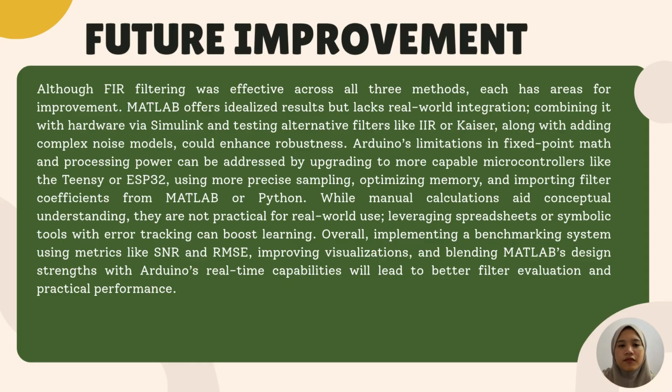Arduino's limitation in fixed point math and processing power can be addressed by upgrading to more capable microcontroller like the Teensy or ESP32. Using more precise sampling, optimizing memory, and importing filter coefficient from MATLAB or Python.